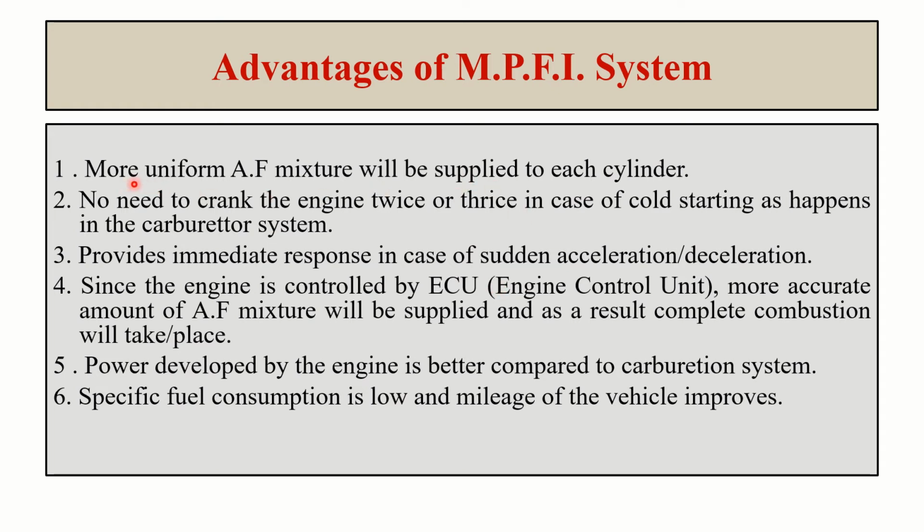So you can see now a more uniform air fuel mixture will be supplied to each cylinder. No need to crank the engine twice or thrice in case of cold starting, as happens in the carburetor system. I think there will be warming up; that facility is there. I have indicated it in one of the diagrams. It provides immediate response in case of sudden acceleration or deceleration, meaning it varies the air fuel ratio depending on the requirement.